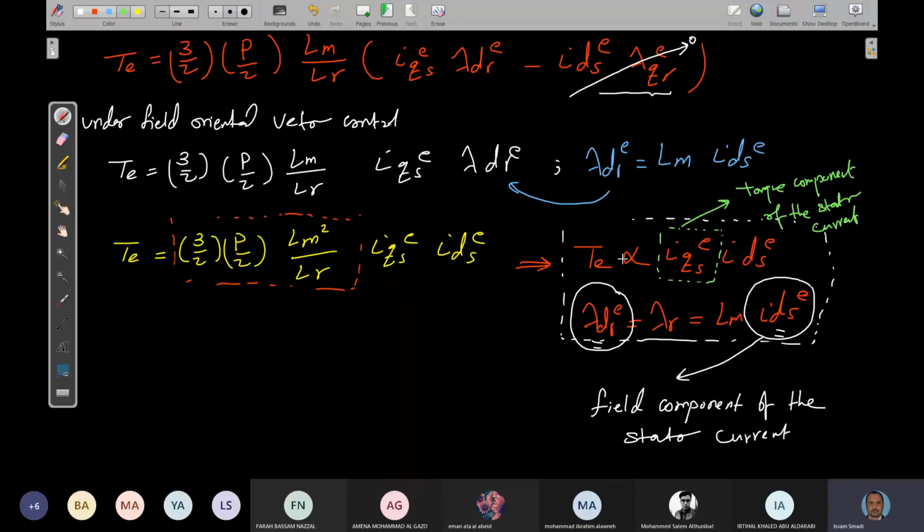So now the question: what about if I'm having a phase difference in the initial phase stage? I'm not that lucky to put my reference frame in the direction of the rotor flux. What I can do is assign it in space anywhere, and rotate it at synchronous speed. Yes, I can do that. But can I make sure that my selection is 100% perfect? No, of course I cannot.